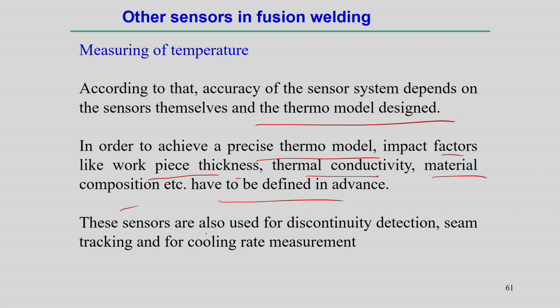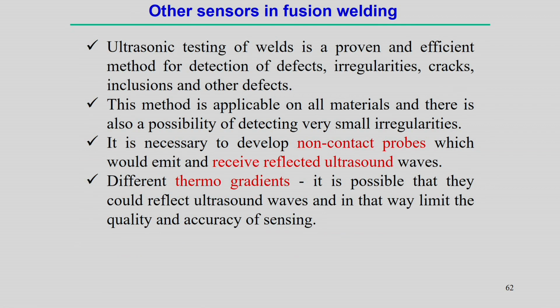These sensors are also used for discontinuity detection, seam tracking and cooling rate measurement. All this sensor data can be analyzed so that we can measure discontinuities. If a discontinuity happens during the process, we can detect it through the temperature, and of course we can also determine the cooling rate from the temperature measurement.